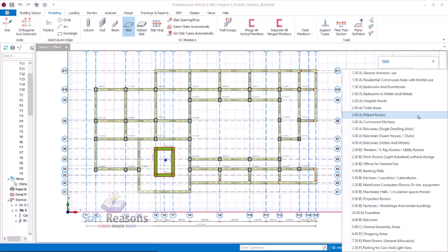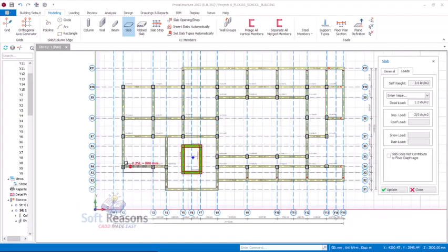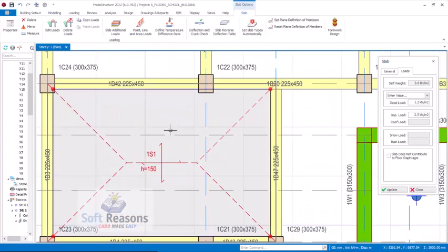For the imposed load for a commercial building, you can see here communal. You can decide to use hospital, ward, and school. We have offices for general use. So we can decide to use 2.5 kilonewton, after which we will proceed to insert the reinforced concrete slab. So we have our slab here. You just have to click in the provisions to have it placed successfully, just like this.